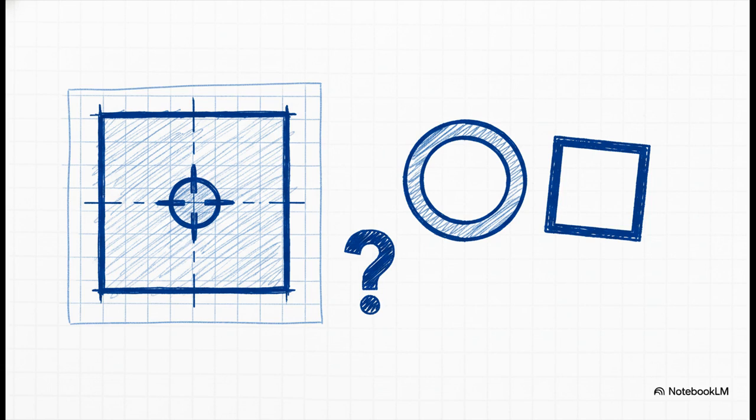Okay, so let's check out a classic example. The old way of locating, say, a hole might define a little square area where the center of that hole has to be. But wait a second, the hole is round. Does a square boundary for a round thing really make any sense? And this is the power of GD&T. There's a method called true position that defines a circular tolerance zone instead. Now, that's a simple change, but look, it perfectly matches the round feature it's trying to control.